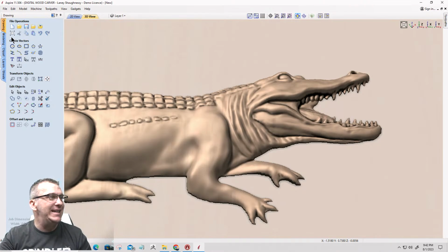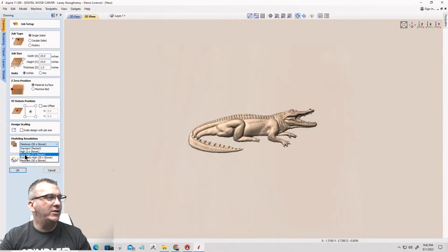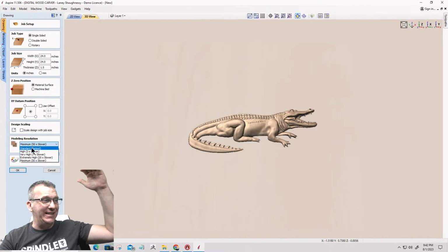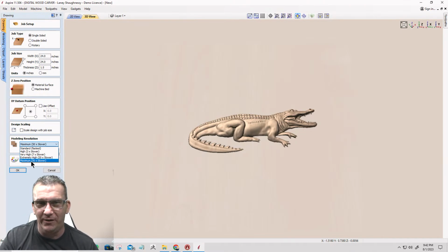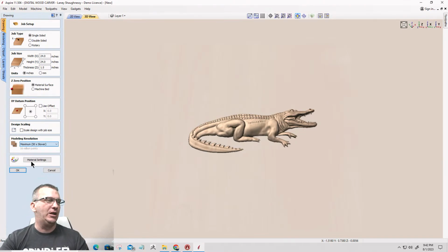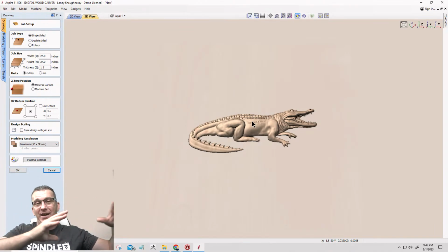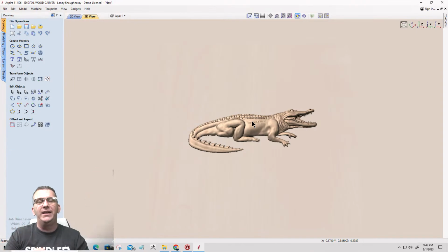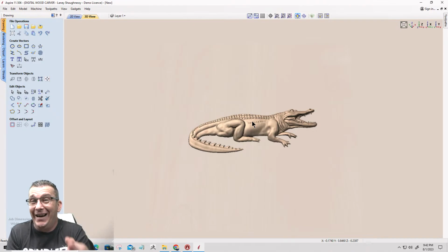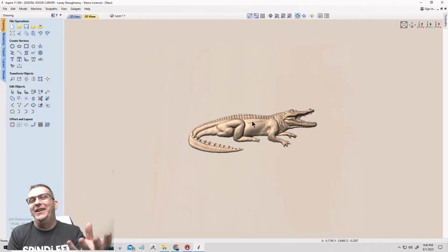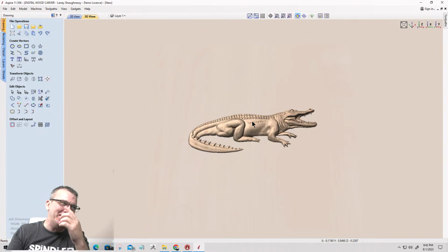That's why you see fastest, right? Basic standard resolution is fastest to generate tool paths and previews. Slow, 3 times slower, 7 times slower, 20 times slower, 50 times slower, right? 50 times slower. So to generate the tool path, to calculate the tool path, to generate the preview and all that, it's going to be 50 times slower than what it normally would be in your standard resolution. But the quality of the cut's going to be 50 times better, in a sense. Not really.